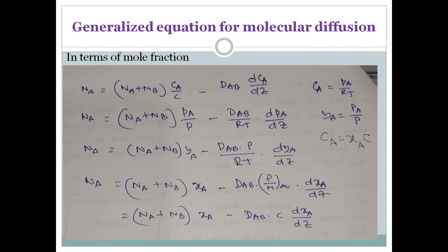So today what we have studied is that we have derived the generalized equation for molecular diffusion, and we expressed it in terms of concentration, in terms of partial pressure, and in terms of mole fraction, in both the gas phase and the liquid phase.